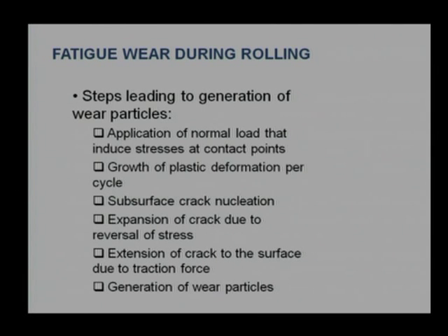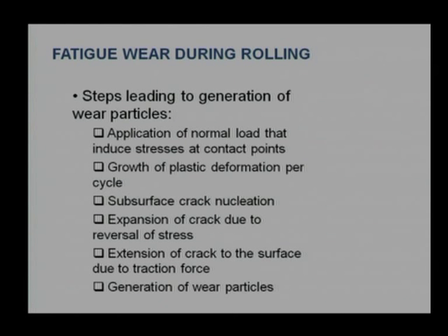And once a dent shape comes on the surface, then problems will start. We say that after dent shape or plastic deformation, there will be subsurface crack nucleation, the possibility that the dent shape itself is generating a nucleus for the crack. And on reversible loading, continuous loading and unloading, there is a possibility of expansion of the crack, subsequent extension, and finally generation of the wear particle.